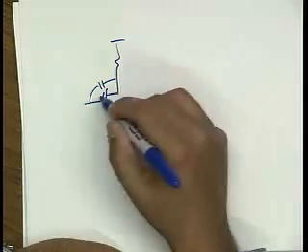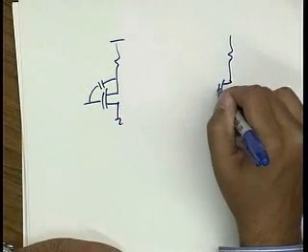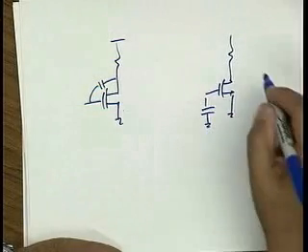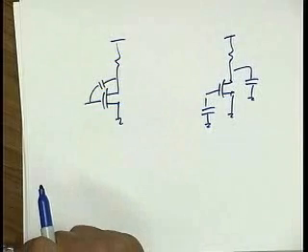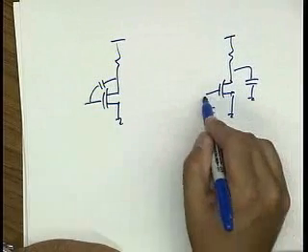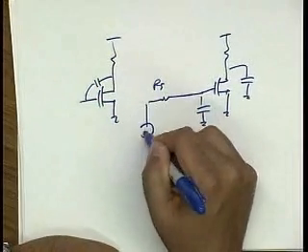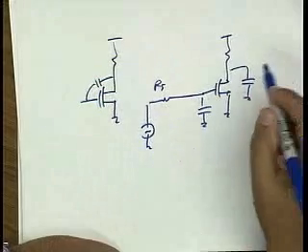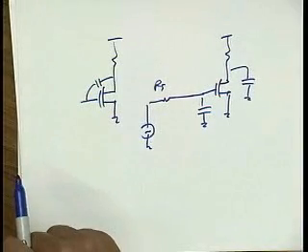So for instance, if I take this same amplifier, which has some effective input capacitance and some effective output capacitance, let's say we do a Miller transform here. We know that this input capacitance is interacting with the source resistance to produce a pole, and the output capacitance is also interacting with the output impedance to produce a pole.